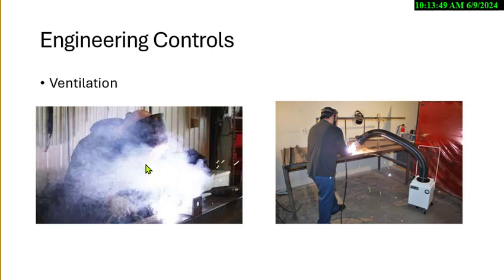You can be a billion-dollar company, and I see workers working and the smoke's going over here. For a few $1,000s, this thing can take away all that smoke. And that's what you want to do. Welding smoke, nothing is good for you. And depending on what they're welding, it could be even worse if they're welding on stainless, because the chromium fume is a cancer-causing metal.